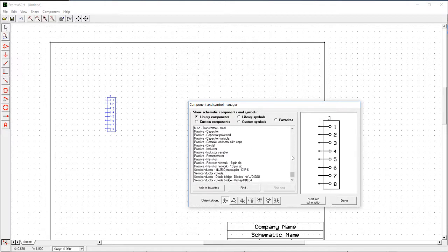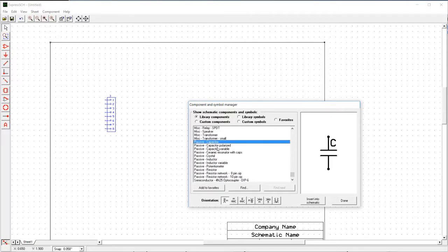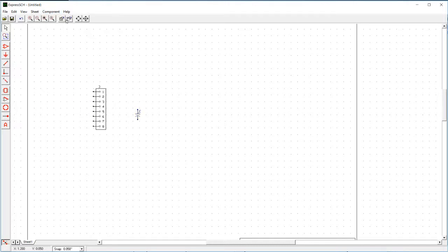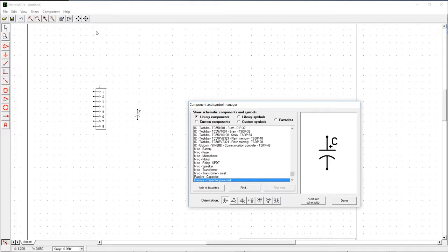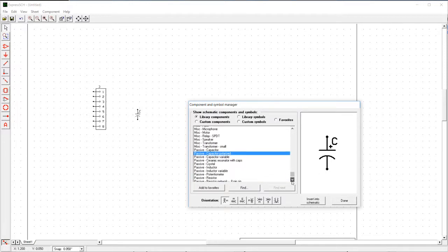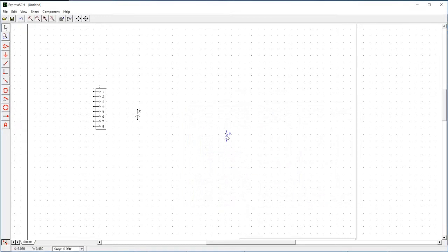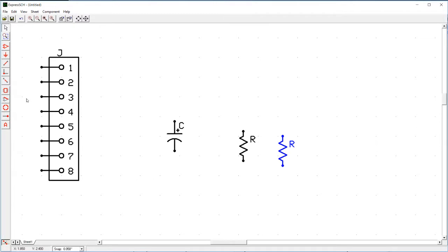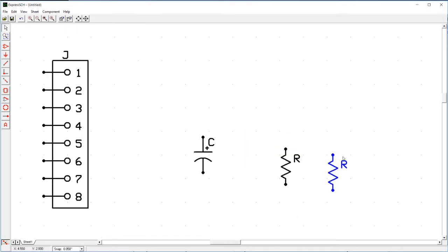There's a number of passive components that you'll find helpful. There's a capacitor. We'll want the polarized version of that because our capacitor in this project is polarized. One of these is here it is. So this is the shortcut. I also have a couple of resistors, so I'll go ahead and add that. And I'm just going to Control C, Control V to copy and paste. And now I have 2 resistors, and I'm going to zoom in because this got small. The scroll wheel, rather, zooms.